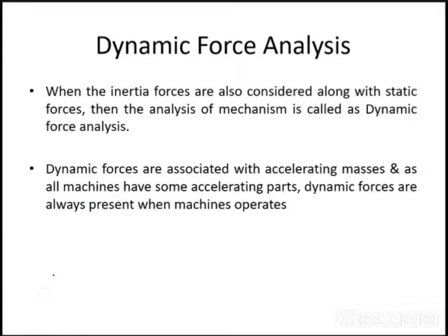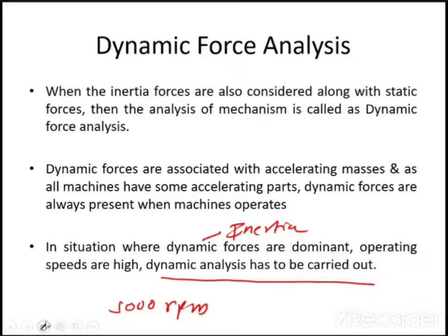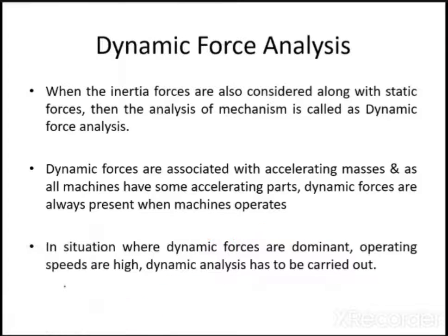Is it clear? But when they are not negligible, you have to consider them, and we call it dynamic force analysis. Next, in situations where dynamic forces are dominant and operating speeds are high, dynamic analysis has to be carried out. Dynamic forces being dominant means inertia forces are very high. Operating speeds are high means, let us say your IC engine is running at 5,000 RPM. The operating speed is very high, so dynamic analysis has to be carried out. You cannot only do the static analysis. Is it clear?